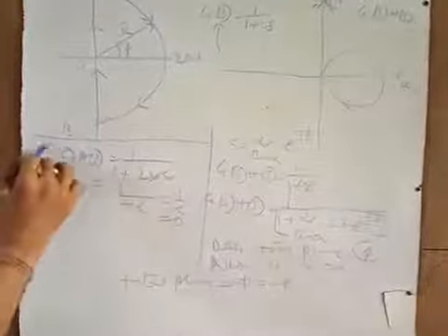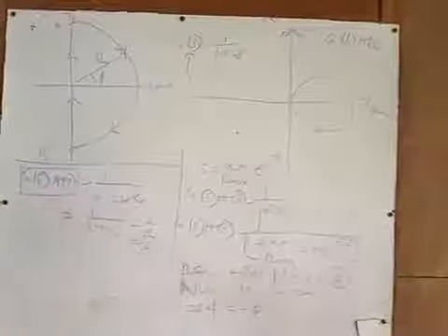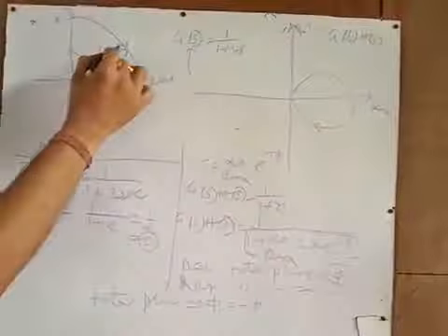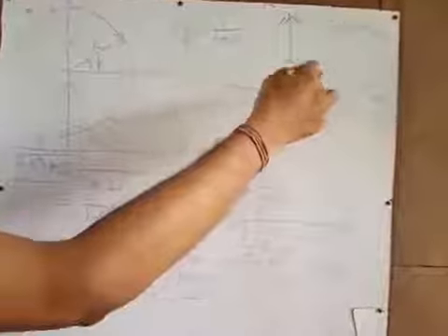So once you vary the value of s from this point to this point, from A to B, this contour part, which actually encloses the complete right hand side of the s plane, maps to 0 if the value of r is equal to infinity. So this part maps to this point. Ultimately the total contour becomes similar to the previously drawn contour.